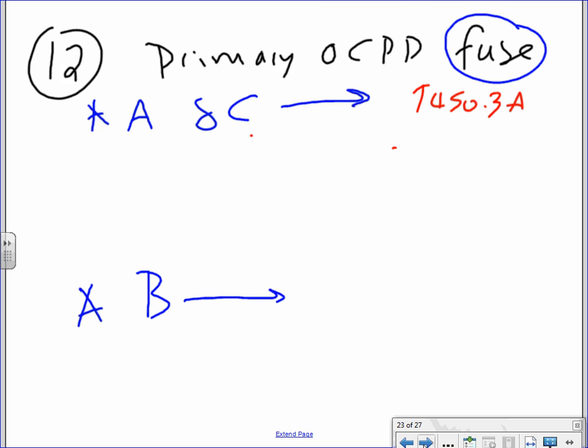For the fuses, we're going to use table 450.3a. Why A? Because one of them is higher than 600 volt, guys. And I'm not going to go to the table anymore because you guys are experts in the table business. So I will remind you, primary overcurrent protection device, A and C. What was the total on the primary side? So the first thing you need to do is I primary line was 94. Was it 94? 93.3 amps. Okay, you might have to check that one for me.